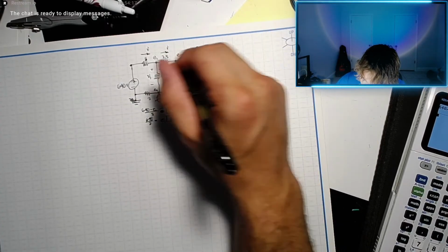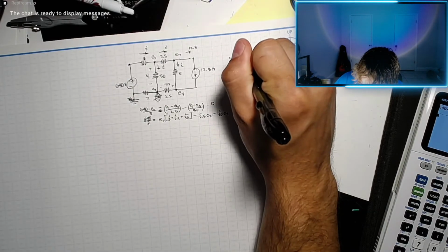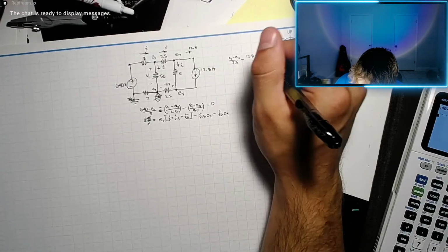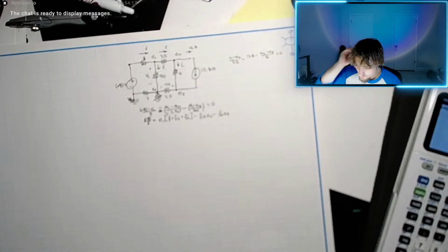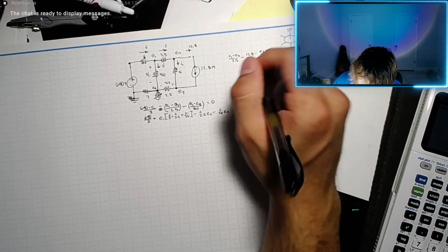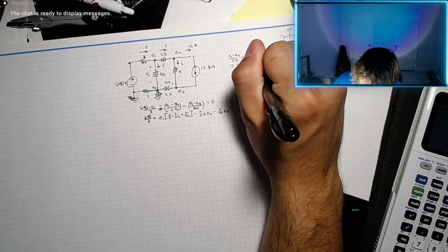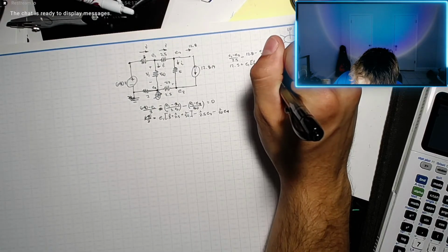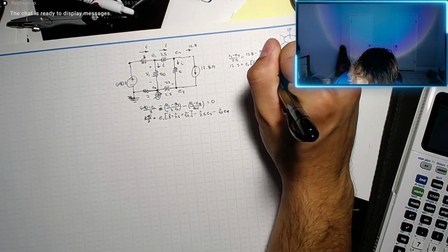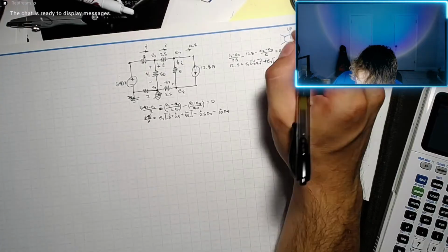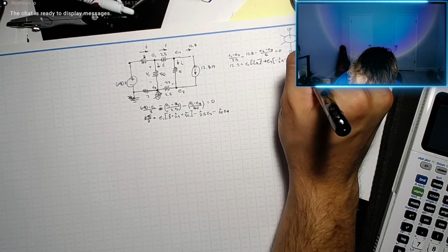Okay, and then we got E1 minus E2 equals E2 divided by 2.5 minus 12.8 minus E2 minus E3 divided by 5 equals 0. 12.8 equals, add it to that side, so E1, 1 over 2.5, plus E2 multiplied by negative 1 over 2.5 minus 1/5, plus 1/5 E3.